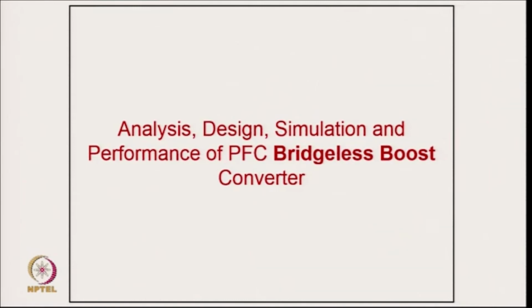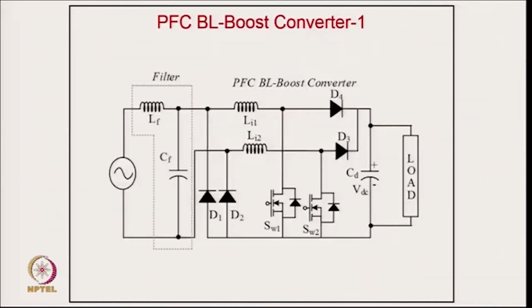So, now coming to analysis, design and simulation of performance of the PFC power factor correction bridgeless boost converter. This is typically the bridgeless boost converter. You can clearly see here that we have eliminated the bridge. In one positive half cycle one boost converter works, and in the negative half cycle another converter works. We call this the power factor correction bridgeless boost converter configuration 1.